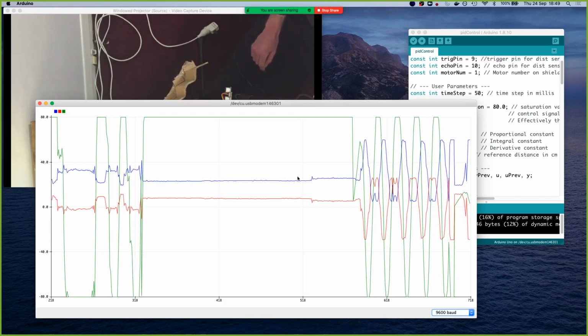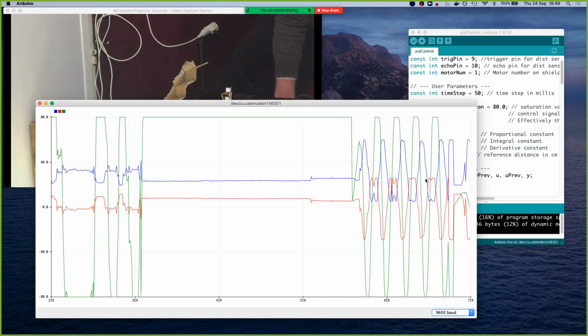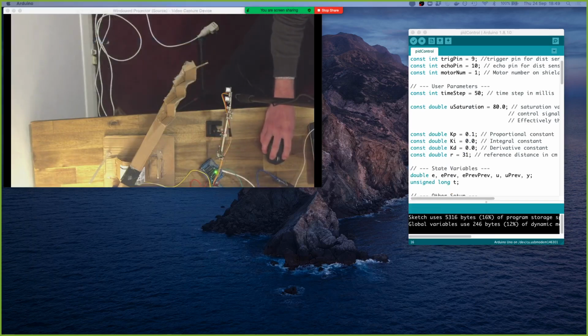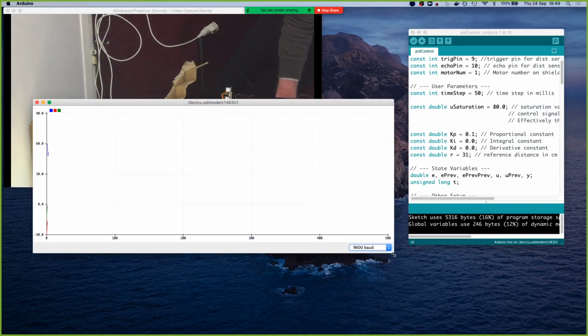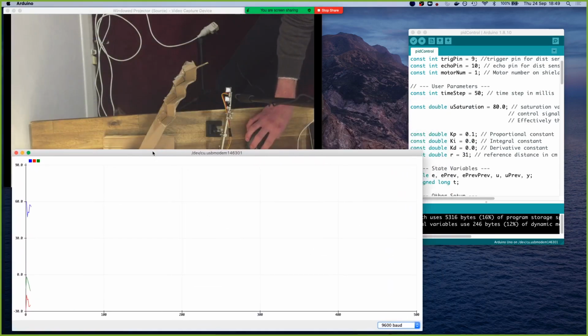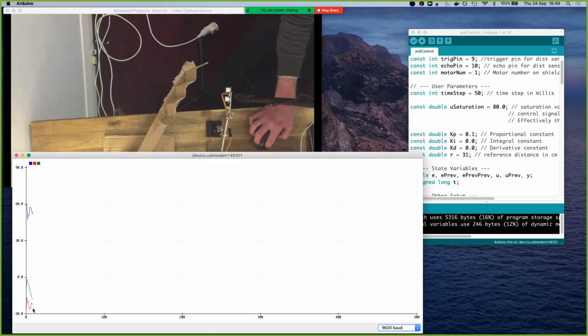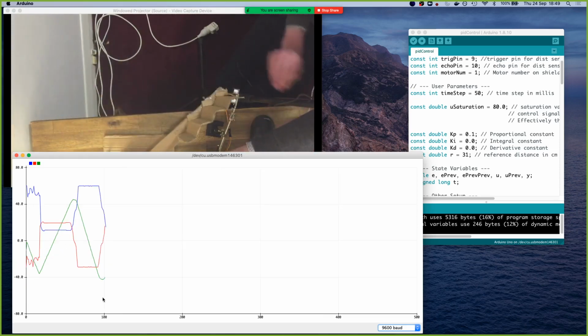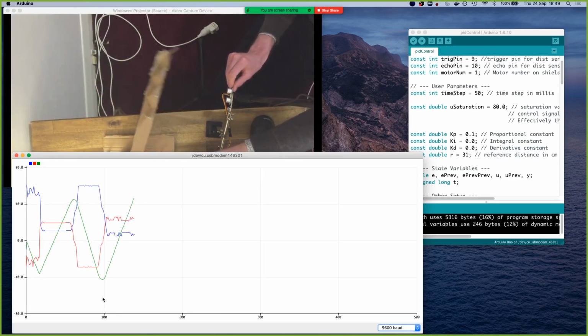So with a quite small proportional gain, you can sort of see it. I might just close that off so it becomes a little clearer. With a quite small proportional gain, I don't know, you guys probably can't hear that, but the motor is whining away. It's getting a little bit more. It's starting to go now. There we go. We're getting control back the other way, swings it back. It's still not quite an ideal situation.